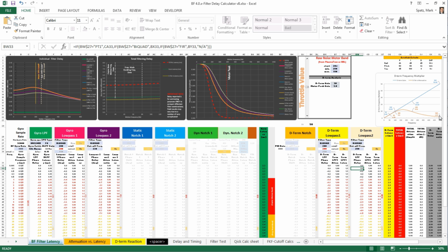And then up at 500 hertz, it's almost equivalent to what you would get at your normal operating frequencies, your control frequencies for motion. I would say if you can keep working it and keep raising up these low pass filters for prop wash tuning and whatnot, what is a good value? 4 is a good value. Honestly, I'm at the point right now I want to be at like 3.5 or 3. I really want to get these down.